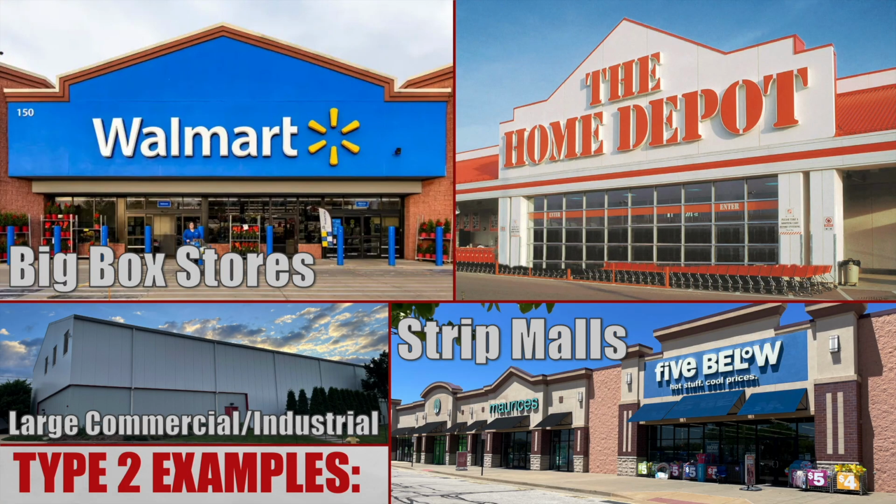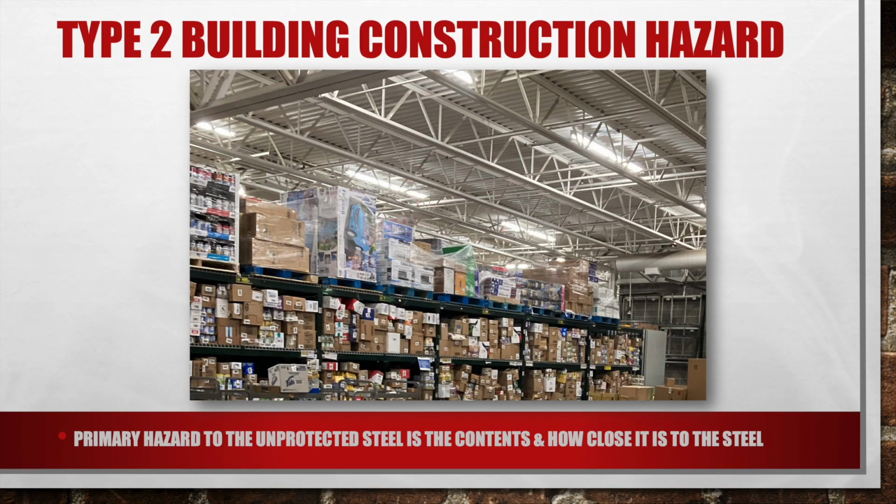So some examples of type 2 buildings include big box stores. So on the top left, we have a Walmart, and the top right, we have the Home Depot. And next time you go into one of these stores, just look up and you will see unprotected structural steel in the roof system. The bottom left picture is a large commercial or industrial building; these are usually type 2, and a lot of times strip malls are type 2 building construction. So, a type 2 building construction hazard.